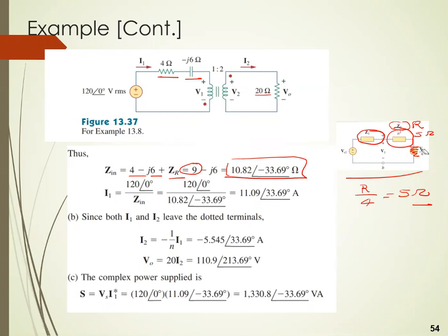All right, but remember, this is the more general case when you have a source on the secondary side. In this example, we don't have a source on the secondary side, so it's just a resistance. So now I just have a circuit. I converted everything into this circuit, and let me do it again since it makes it easier to understand. I don't have a source on this side, you just have a wire, and this impedance is replaced by a 5, which is a reflected impedance now.